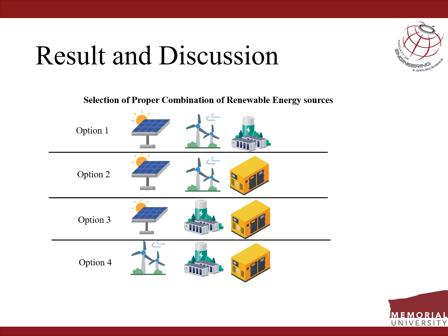Option 2 is the combination of the existing diesel genset, PV panel and wind turbine. Here the advantage is the less initial cost of PV panel and wind turbine, alongside the replacement cost of the battery. It is also suitable for the economical calculation generated by Homer Pro, though there are some drawbacks, since the PV power cannot be used at night time or in cloudy days, and it is still required to depend on diesel, especially in winter time, which increases the complexity because the power supply is very crucial in winter.